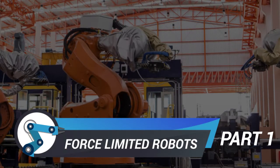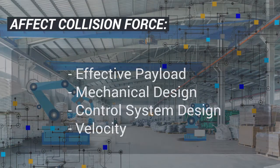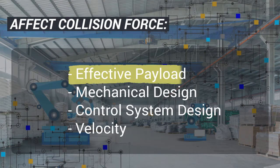In this lesson, we will get into a bit more technical detail on factors that influence the collision forces for a collaborative robot. Some of these factors, such as mass and velocity, are fairly obvious. However, some other factors, such as reflected inertia and the control system design, are not so obvious. ISO 15066 refers to effective payload in several places. We will explain the items that contribute to effective payload.